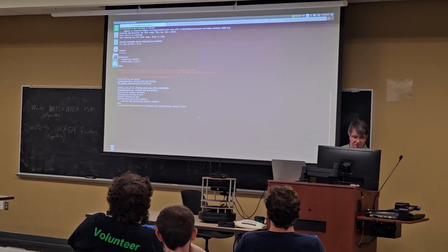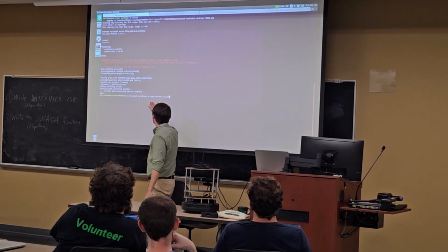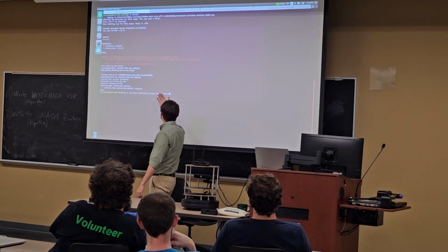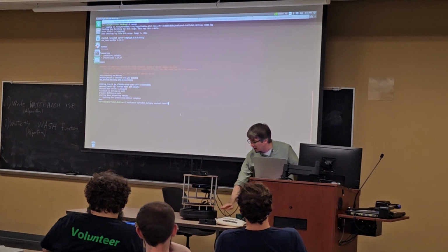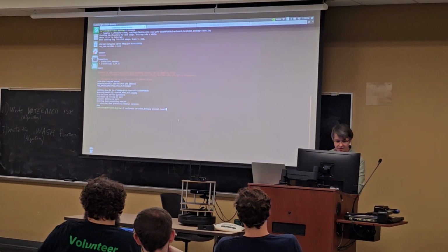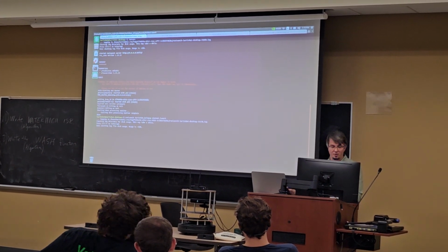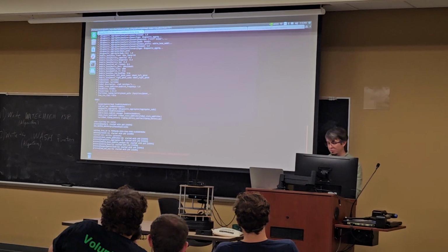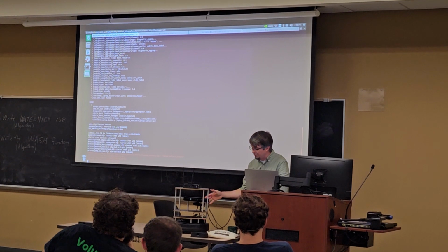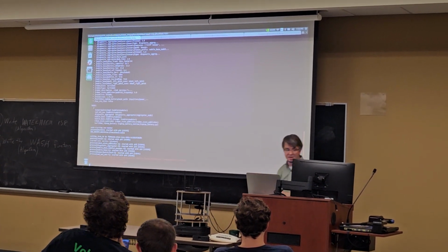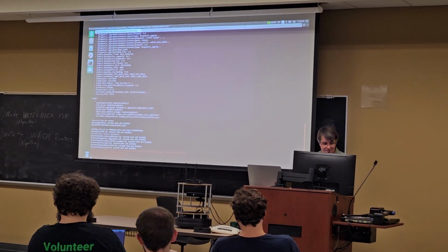So I'm going to use a command here called roslaunch, with the package turtlebot_bringup and minimal.launch, and that's going to bring up basically just what this thing needs to communicate with the robot base. If I do that, it's going to launch the ROS core, and also everything, all the other programs that it uses for driving this base here. So we heard that little jingle, so it successfully connected.